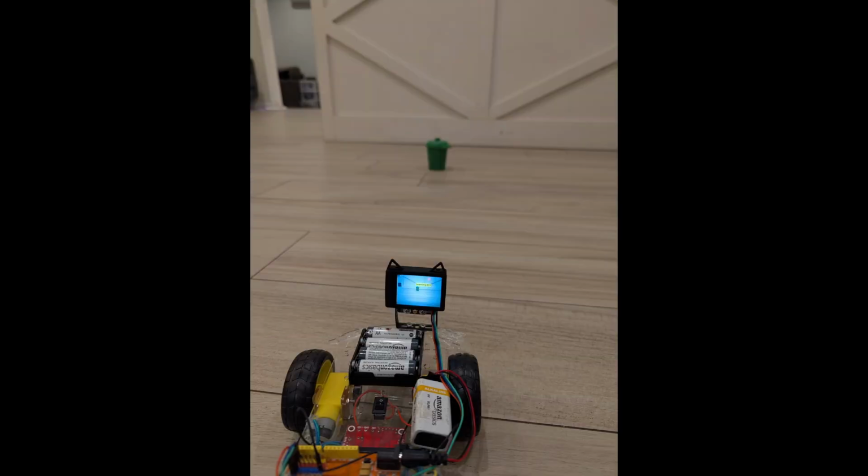Now the last two clips that I want to show you really helped with the HuskyLens. It's not a very fast camera. It's not great at catching live action. And so what I did in the code, which I didn't mention explicitly, is that for every 50 milliseconds of driving, I did 50 milliseconds of stopping. And what that does is it makes the drive very jittery, but it really slows down the speed of the car by half, so that every frame of the HuskyLens, you have a chance to reassess it and decide what to do. Here's what it looks like.